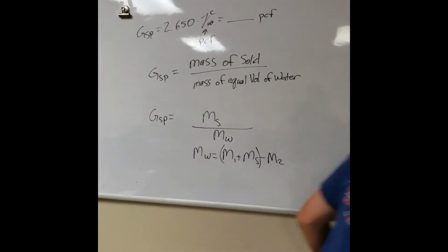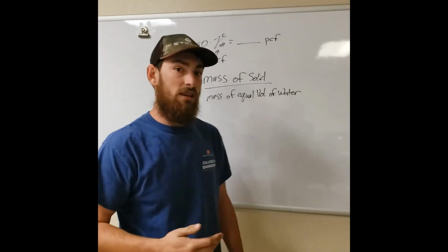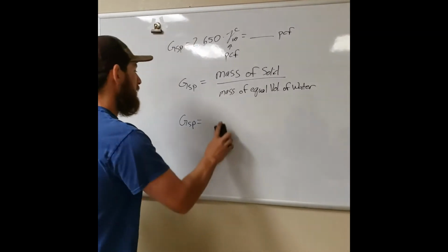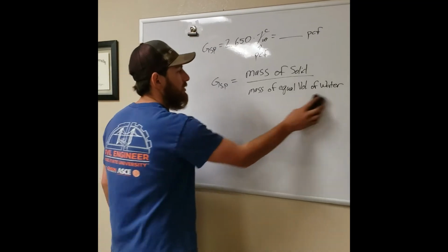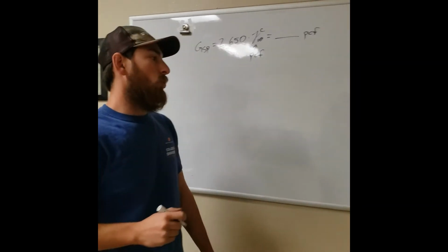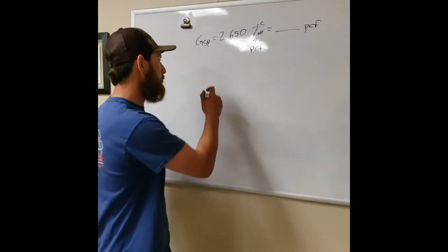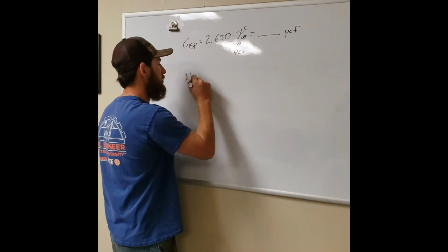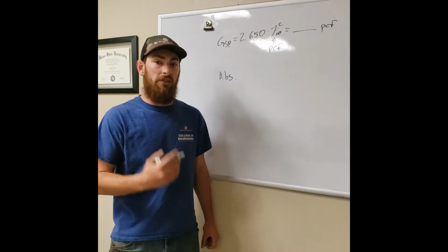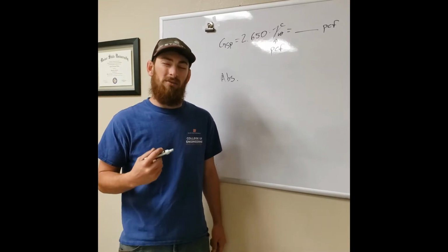Now, for the coarse aggregate, it's basically exactly the same. It's just a matter of how we get this that is going to be slightly different. For the coarse aggregate, there is one other value that you're going to need to calculate in your end result, and that is absorption. You can abbreviate it ABS. Absorption, we're not going to get for soils. There is an absorption there, but it's significantly higher in coarse aggregate.